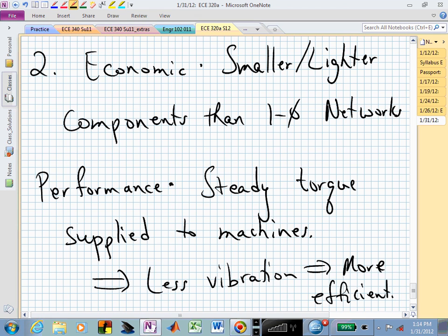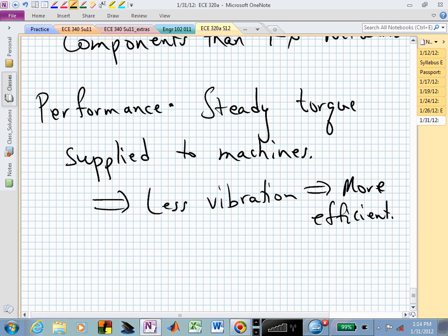With three-phase, what we can actually see is when we have all three phases going, we now have a constant power flow moving. Each phase is oscillating, but once you add those three phases together, you now have a constant, steady flow of power. If that's the case, now we're supplying that to a three-phase machine, and that machine is just nicely, smoothly spinning. Instead of going high, low, high, low, high, low with the machine, and it's trying to respond, and it gets a little rough, now we have a smoother supply on these machines, leading to less vibration and a more efficient system in general.